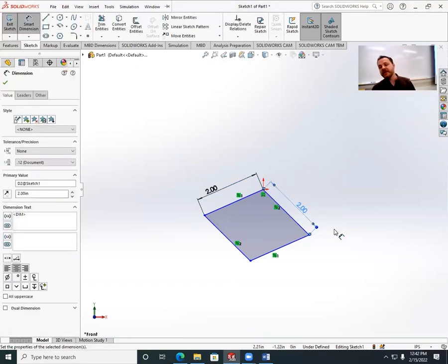Now because I've set all these sides parallel, this is what we call a parallelogram. And so I don't have to define these other dimensions. If it's been a hot minute since you had high school geometry, I understand you may not remember that, but you do not have to define these lengths. That's already defined by these parallel sides.